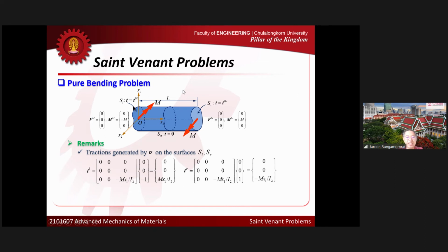Once I apply the traction at both ends of this particular form, now I can say what? I can say that the solution that I got before is the exact solution. Okay, exact solution in the sense that it can be a solution at every point of the body. Or I can say that the simplified or the original boundary value problem are identical for that special case.